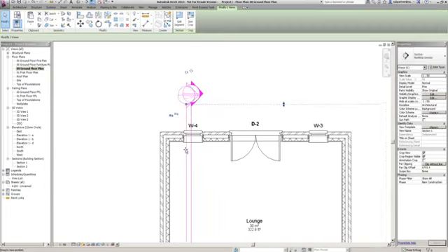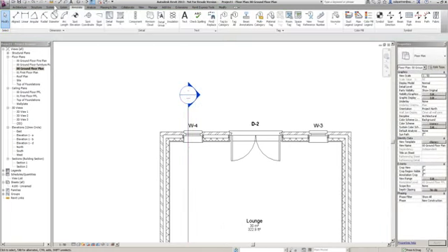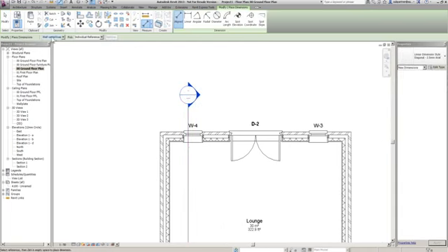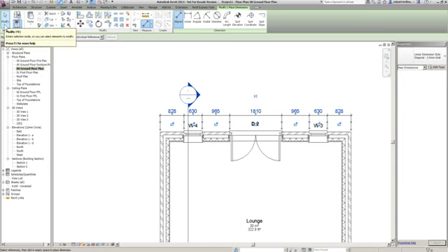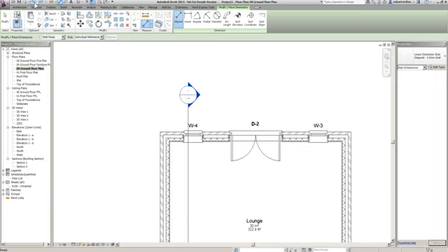Okay. Now, obviously, we can use dimensioning by going Aligned Dimension, not wall center lines, wall faces, and I could just dimension from here to here to here to here to here. You know, pretty much a standard CAD way, and place that. Now it's quite nice because you've got the continual way of doing it. But what I'm going to do is show you how Revit does it, because this is Revit, it does it a little bit better than that.